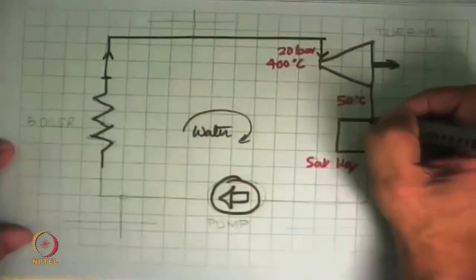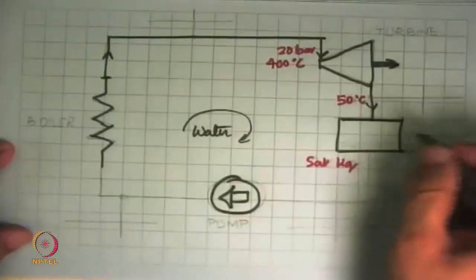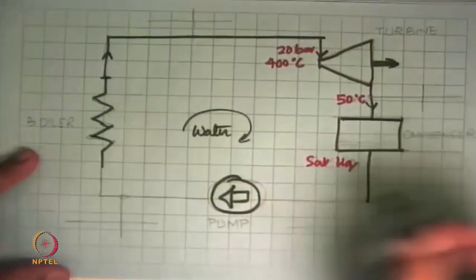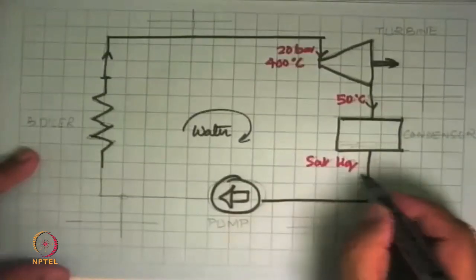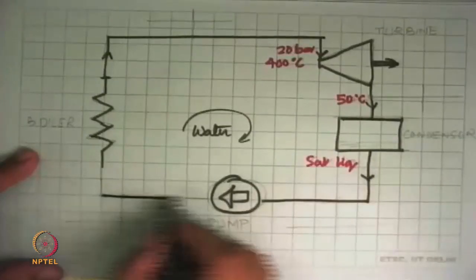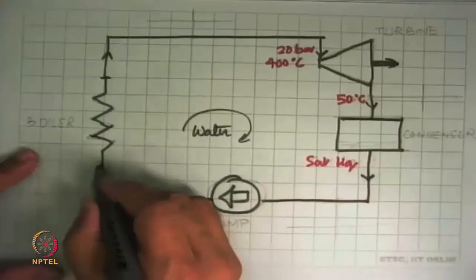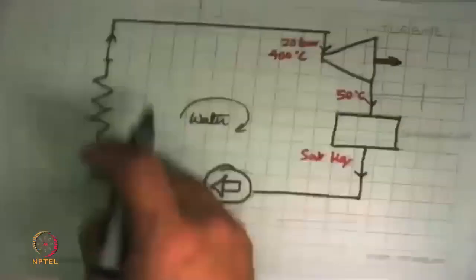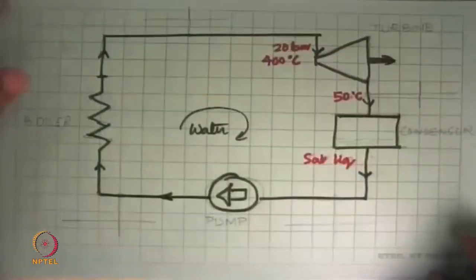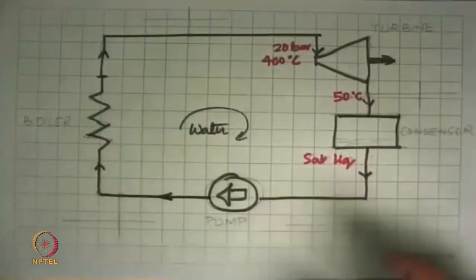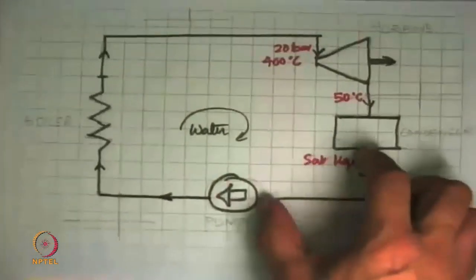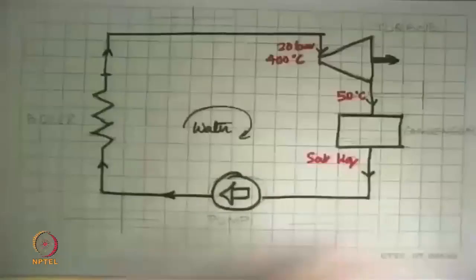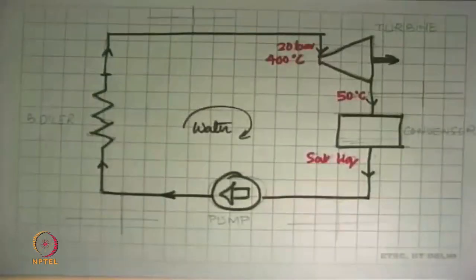The turbine exhausts the steam and comes into the condenser, where it flows over tubes carrying cold water and becomes saturated liquid and comes down. This flows into the inlet of the pump, which flows into the boiler. In a real power plant, some of these pipes could be like 100 meters long, 150 meters long. Some pipes could be small. For example, this pipe could be just like about 3-4 meters. And this would be even smaller than that. So that doesn't matter for us.